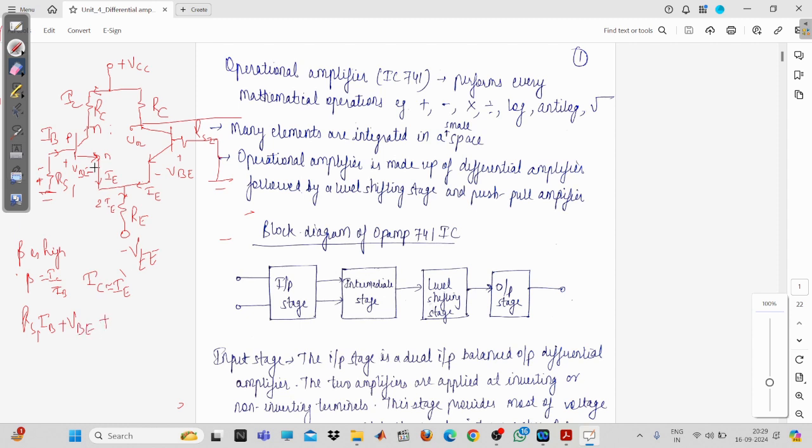After that, there is a wire, we can say. So now you can see here IE plus IE, these two currents are entering into the node. Fine. And then this current has left the node. So now it is flowing through the RE. So when it is entering into RE, we will have to mark that as plus, and this one is negative. So you can see that the current is moving from plus to negative. So that will be counted as the voltage drop, and normally in my sign convention I take it as positive. After that we will be having the negative power supply. So this is the thing.